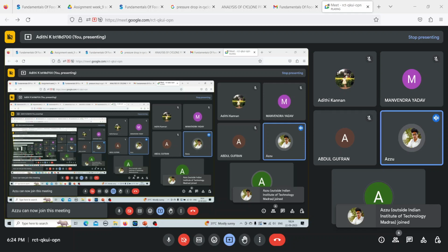So for oil mills, generally discontinuous type pressure filters are used, where your filtration happens in a batch-wise process, where you have to remove the cake and then restart the process again, and you apply pressure on one side of the membrane so that the filtration process can happen. So discontinuous type pressure filters are what is preferred in oil mills, and the majority of the filters that have been discussed in the video lectures include the discontinuous type pressure filter,